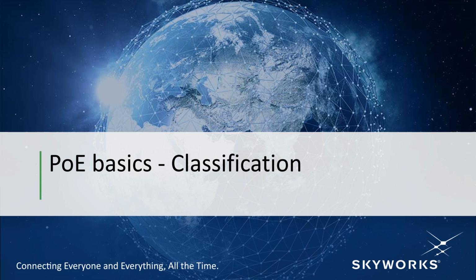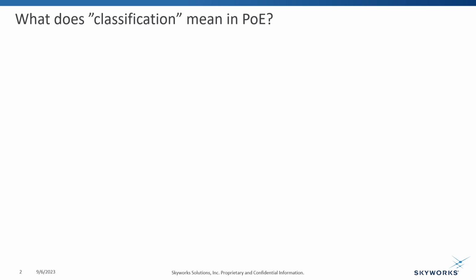My name is Gábor Valentin Csutár, Skyworks Application Engineer, and today we will talk about PoE PD's classification function. First of all, let's see what classification actually means when we talk about Power over Ethernet. After a successful detection, PSE transitions to the classification stage. If you are not familiar with detection, please take a look at our previous video, PoE Basics Detection.